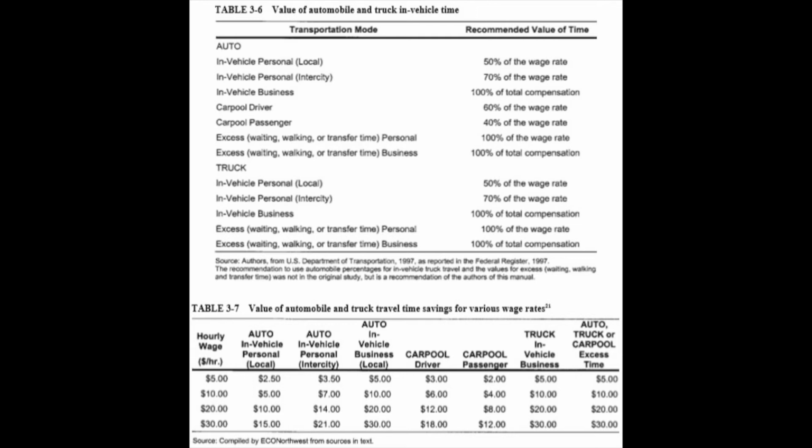Two items of note here. Primarily, you need to have a higher level of income to afford and run a car. Therefore, the trips made via roads, highways and freeways are valued more than those made via public transport, where the only barrier to entry is the cost of the fare. Therefore, the trip made by road contributes more benefits than those made via public transport. Secondarily, there are some cases where an increase in travel time is viewed as a positive in leisure and tourist areas like the Great Ocean Road.